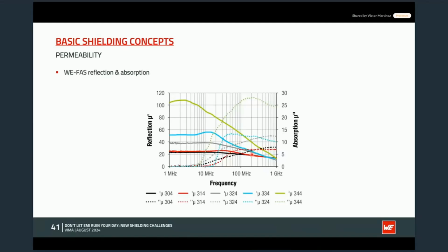Then why is the permeability important? Because at the end, you will find, not only on our website but everywhere, that there are different types of magnetic absorbers. And all of those different magnetic absorbers have different values of permeability. Those values of permeability are mainly determined by the mixture of magnetic materials like the ferrite, the manganese, and some other materials in the mixture, and also by how the flakes are oriented. And every type of mixture is like the secret potions from Asterix and Obelix: every mix has some specific specs.